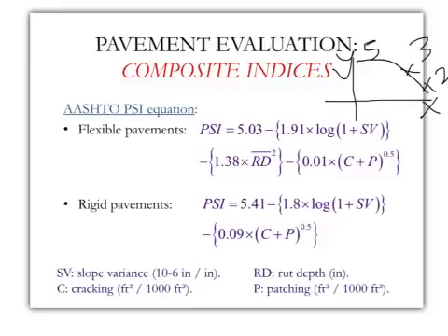Another interesting fact that I also need to mention is that the effect of the slope variance, if you do the math, is going to be the highest factor that contributes to the present serviceability index compared to cracking as well as rutting and patches.